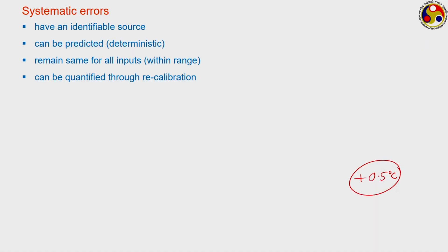And if we have an idea about the corresponding magnitude of zero drift, then, let us say we have got a measurement of 11.2 degrees Celsius from the device, we have to subtract this zero drift from there, and the actual reading will come out to be 10.7 degrees Celsius. So this way the magnitude of the error should remain the same, or at least always go in the same direction, and hence we can somehow eliminate them.